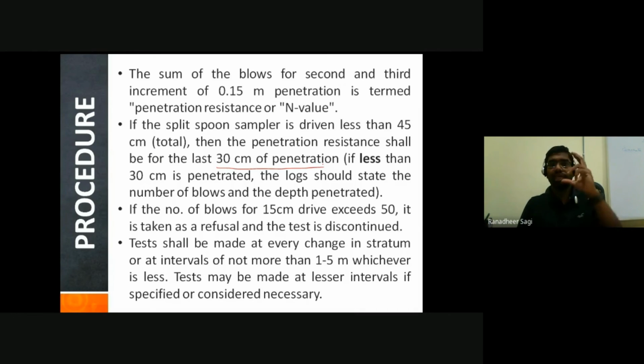Put together, it is 30 centimeters depth of penetration that we are looking at. In the process, the SPT N value we calculate is N2 plus N3.